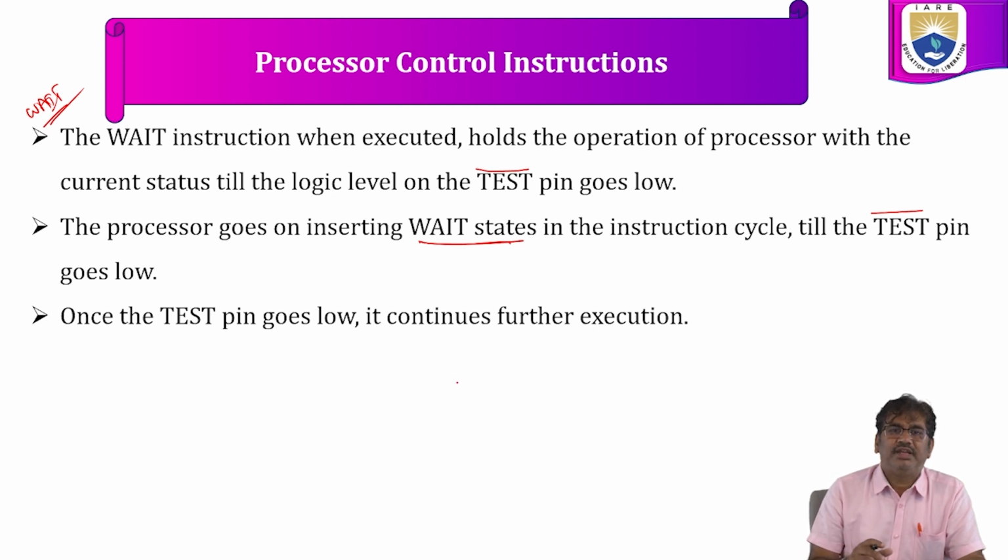Whenever for any cycle like a write operation or read operation, if more cycles are required, then the processor will enter into wait states. Once the wait states are done, it will go for normal execution.